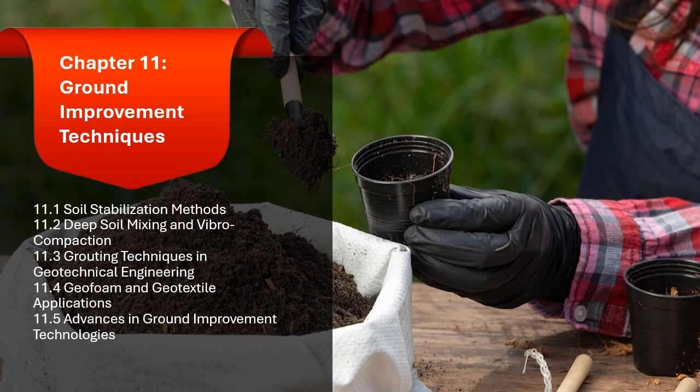1.2.1.1 Process of Deep Soil Mixing. 1. Soil mixing. The process starts with a mixing tool, typically a set of augers or a rotating blade, being driven into the soil at the desired depth. These tools mix the soil with the binder, cement or lime, to create a solidified column or block of improved soil. The binder is typically injected in slurry form during the mixing process to ensure uniform distribution.